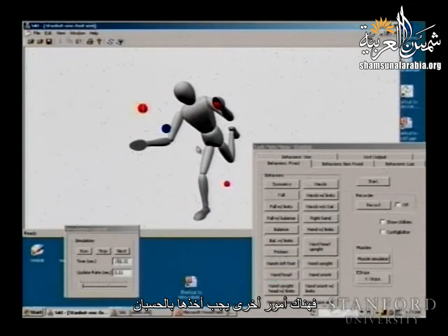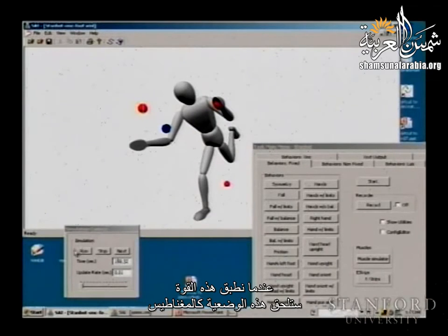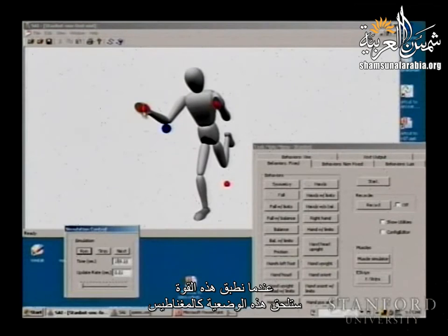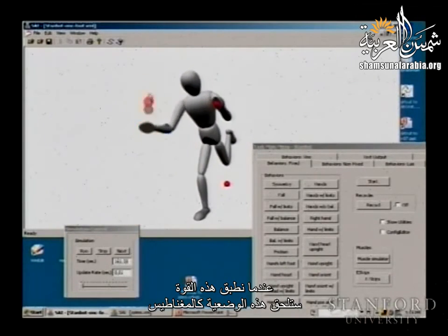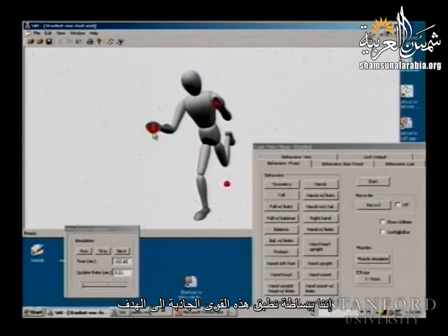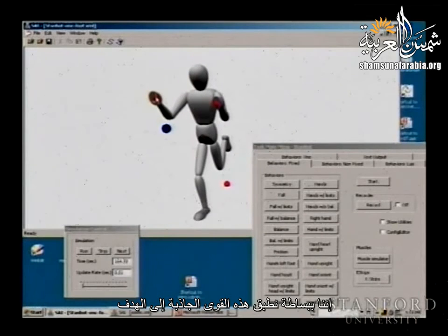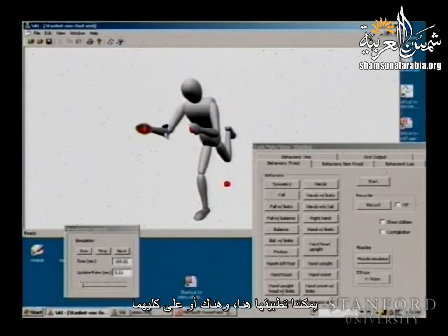So there are other things that need to be taken into account. And what we are doing is we are also applying other potential energies to the rest of the body to balance. So when we apply this force, you see it's just following, it's like a magnet. It's following this configuration. There is no computation of the joint positions. Simply we are applying these attractive forces to the goal. You can apply it here, apply it there, or apply it to both.